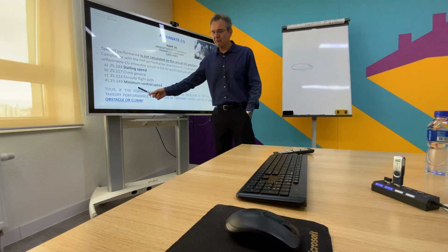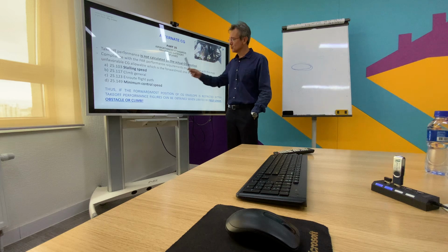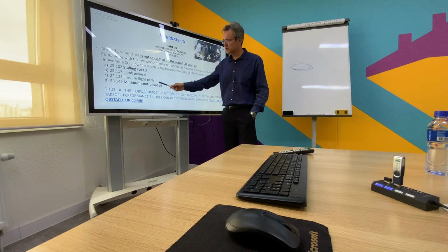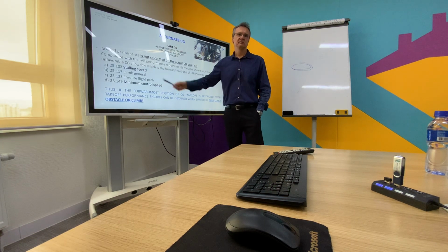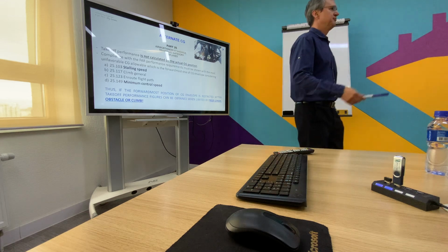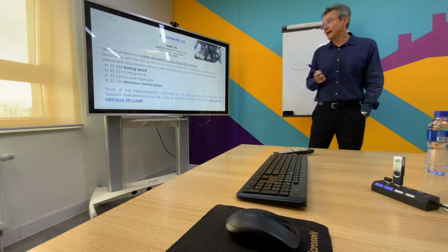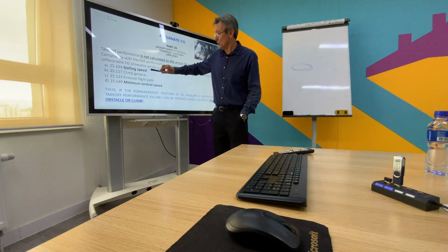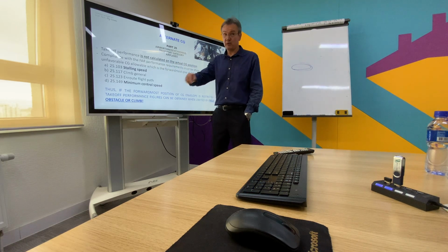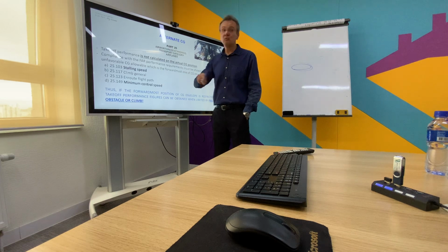To get the takeoff performance, the test pilot has to consider the worst of these speeds for takeoff calculation, for takeoff performance, sorry. Okay? And sometimes the worst is stalling speed right after takeoff and minimum control speed.